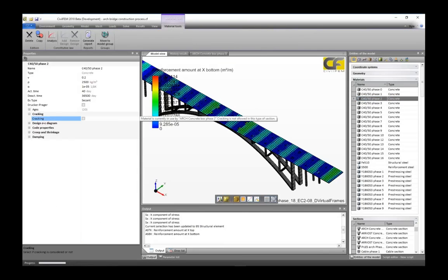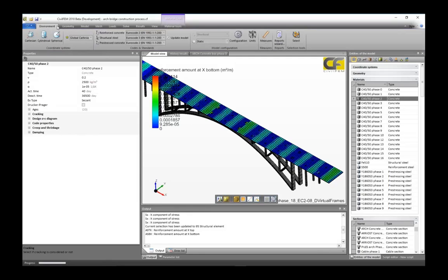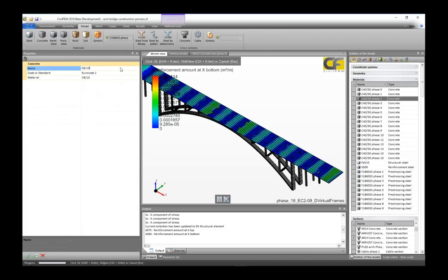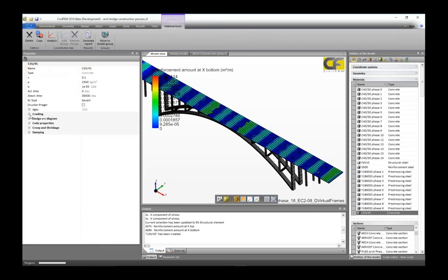First, we click here for cracking, and we activate cracking options. Well, I can define a new material, an example just for you to see. Concrete material. I select any of these, this is an example. And here, cracking, I activate cracking, and then crushing.